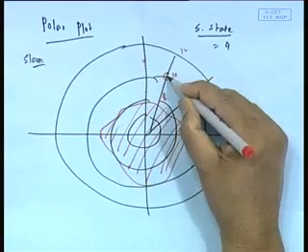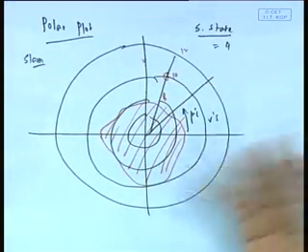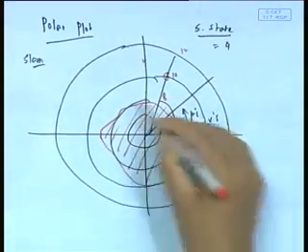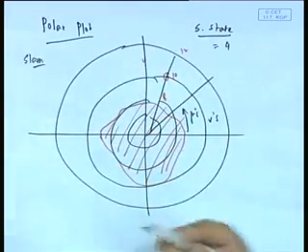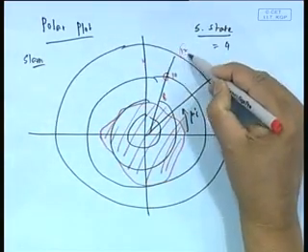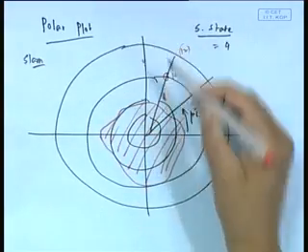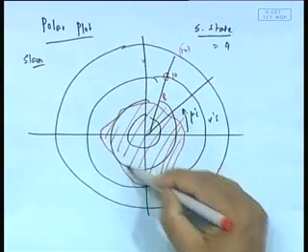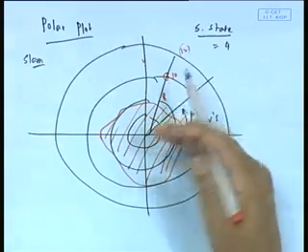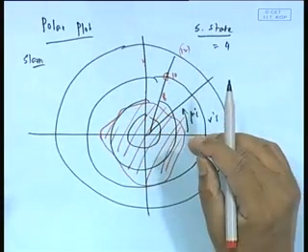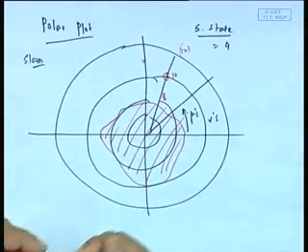So, if it is say 10 knot and this angle or whatever, then I will find my slamming is more than 20. So, this gives me an area, that means the operation zone is defined, maximum speed is say 12 knot here. So, I have this circle as the operation area, right. Now, I find that only in this area essentially my slamming is within the design limit, whatever was specified. So, this was one criteria.